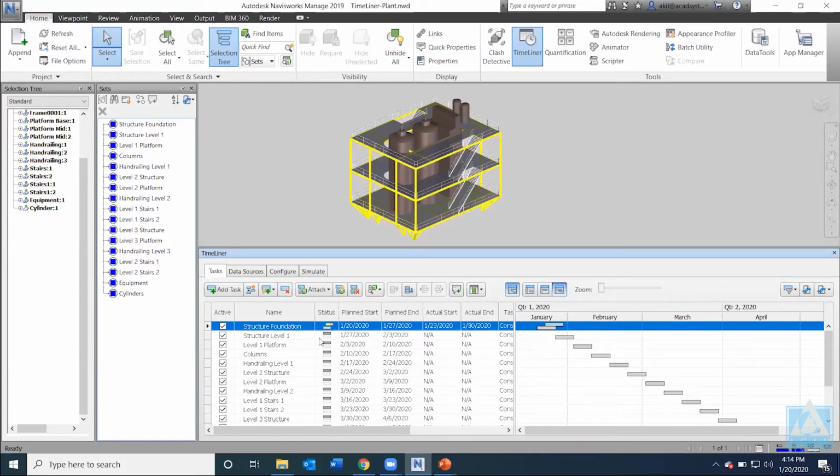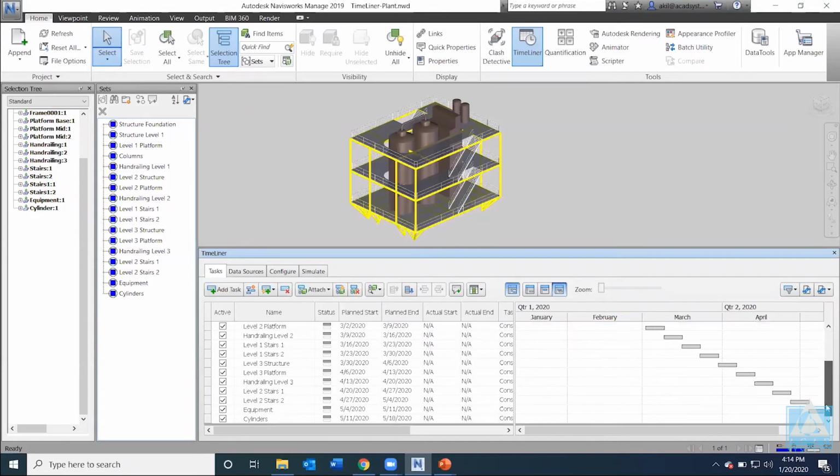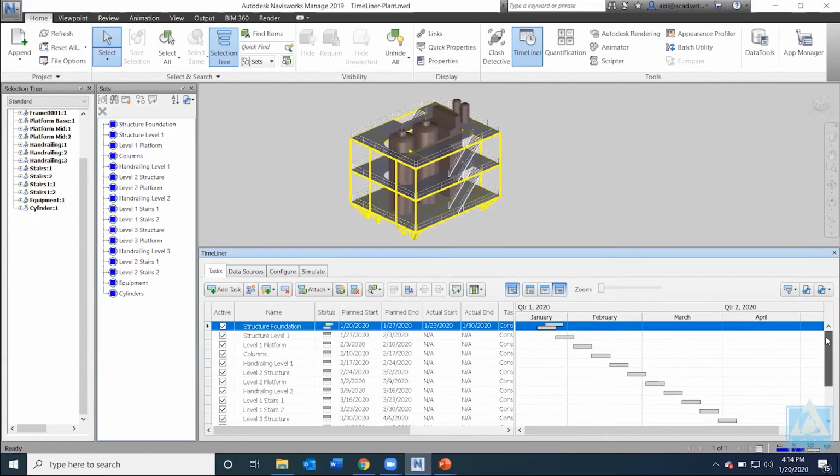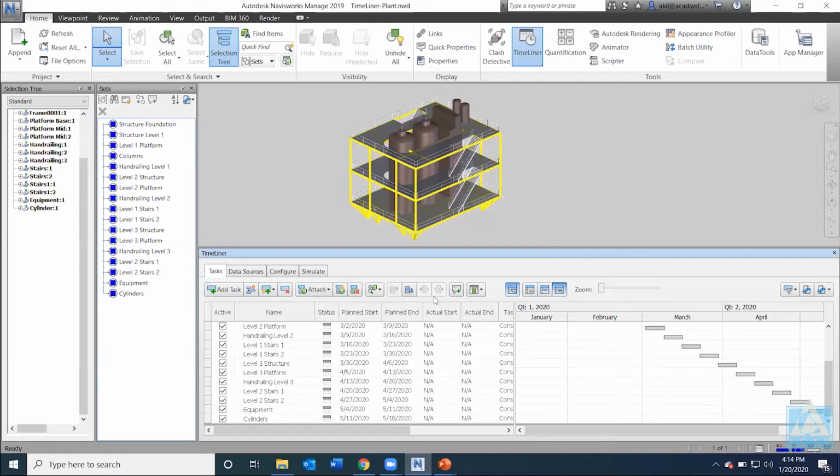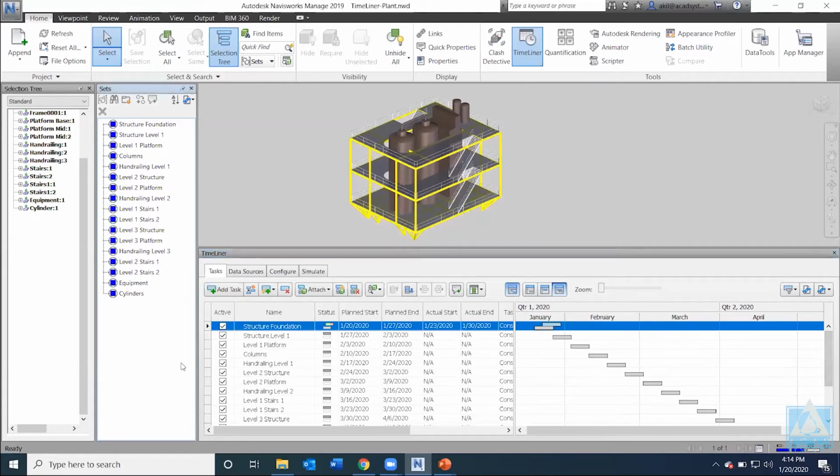The work program may not be as simple as this for a real project, but this is just for you to know the basic features. The way you enter the days or control everything is just the same, right? So let's say we have entered the dates for plan start and plan end, and you have seen clearly that this Gantt chart is updated following what you state in the plan start and plan end.